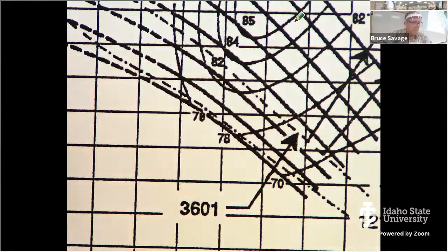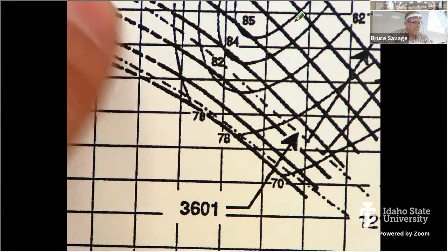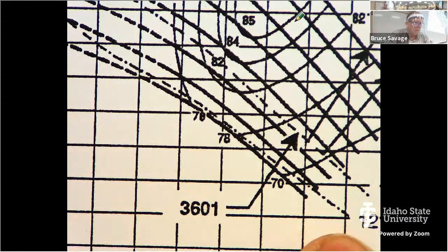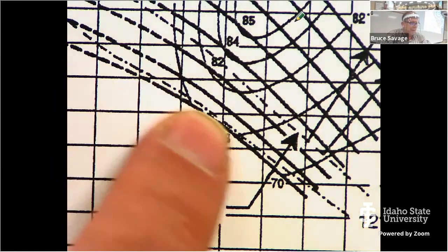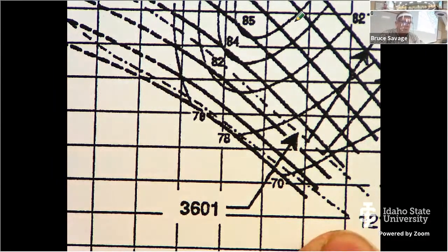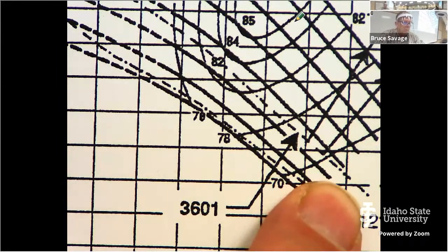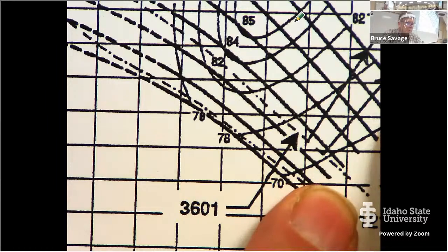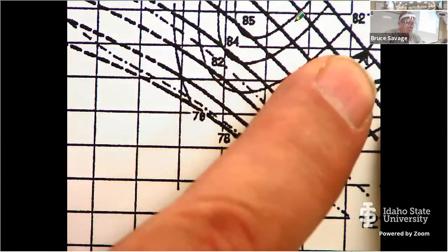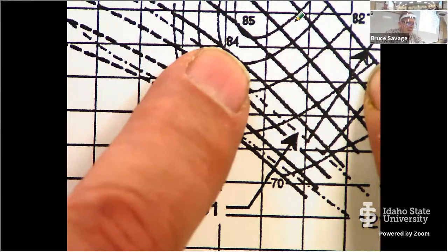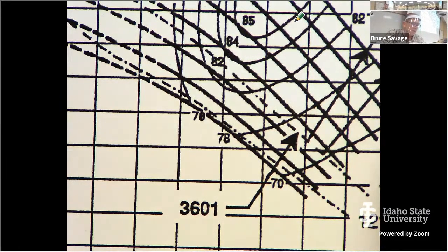You kind of run down through it. Not the ones that are the impeller curves, but the ones below it, the dot dash, dot dash, these two right through here. And they come down to this rating that tells you that if you're down here with this dot dash, the 121 horsepower motor, what they call their 820 motor, is sufficient. And if you're up to the next one, you want to go to the 150 horsepower motor. And if you're on this upper line, you're going to want the 295. And if it gets any higher than that, you want the 3306, I don't know what that is, to be honest.